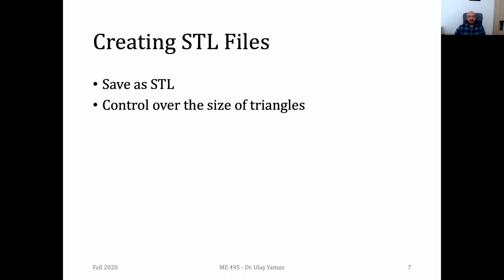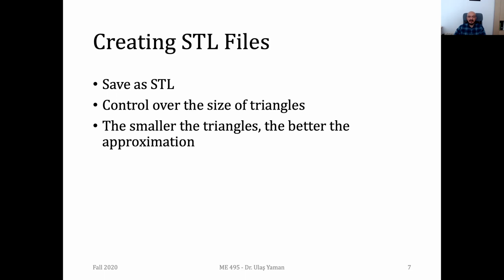In most of them, your CAD software asks you the resolution of your model by setting it to, let's say, 0.01 millimeter or 0.1 millimeter simply. You may play with the number of triangles which are going to represent your original model.